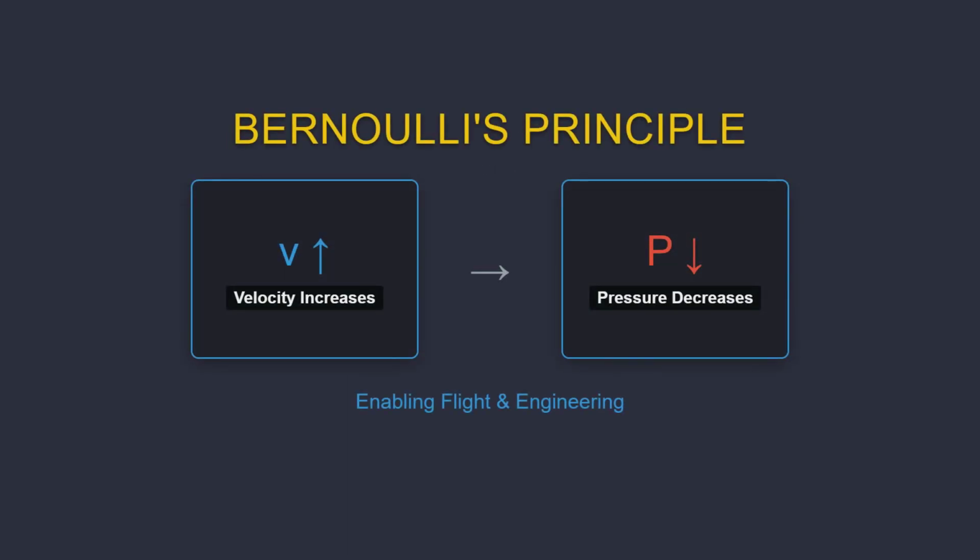The primary mechanism for lift generation on an aircraft relies entirely on the pressure differential created by flow acceleration. The cambered or curved upper surface forces the air to travel a longer path, resulting in a significantly higher velocity compared to the flow beneath the wing. This higher velocity above the wing translates directly to a lower static pressure region precisely as predicted by Bernoulli's principle. The resulting pressure imbalance between the top and bottom surfaces generates a net upward force, which is the aerodynamic lift.